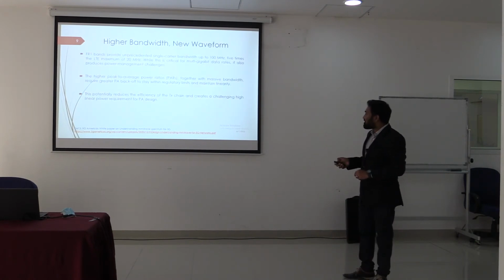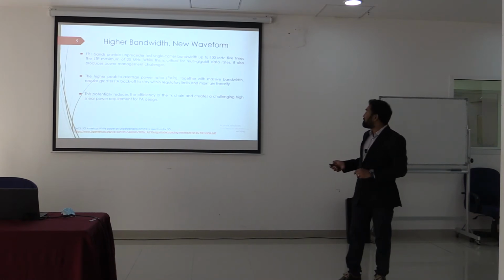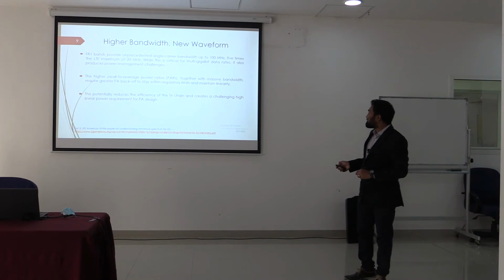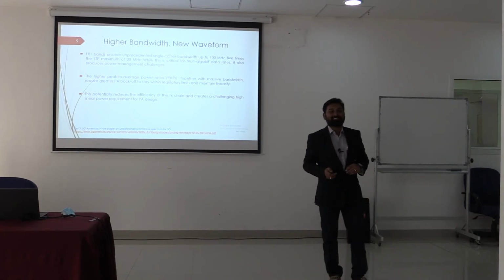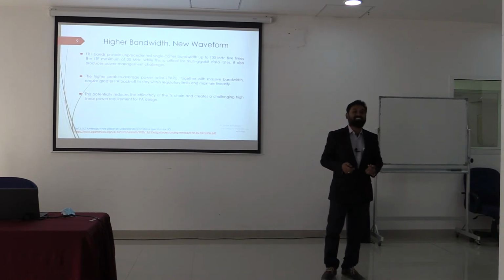So as I already mentioned, that 1 dB compression point in the power amplifier region. So we have to maintain the regulatory limits, that we have to operate our non-linear devices in the linear region. Which amplifier will provide the amplification at the non-linear or linear region? Is it feasible? We are designing a power amplifier. Are you operating in the linear region or in the non-linear region?